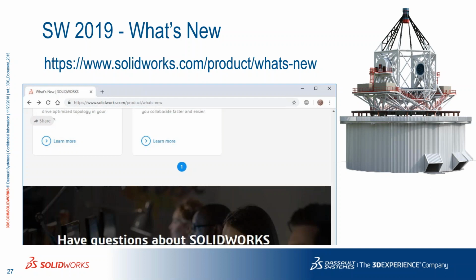All right, I think we have time for one more. How did you magnify the edge when mating the part so quickly? I'm not sure which one that was. That might have been when we used the little magnifier on screen. That's a cool tool we've added. Oh my goodness, that's a long time ago. Hit the G key on your keyboard and a little magnifying glass pops up, and you can still zoom inside the magnifying glass too. As soon as you click outside the magnifying glass, it goes away. So that's a cool little thing, the magnifier. Just hit the G key on your keyboard.